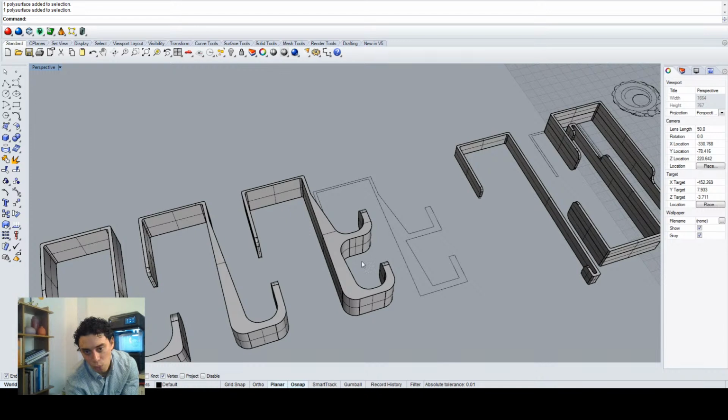I already knew what the thickness right here in the actual hook area was that was going to work for me. What was the simplest way to print it? I already learned about the orientation, the limits even that I had when creating these radiuses. Since I'm going to be printing this part, I wanted to print it without supports, right? So there's a limit to how steep I can make this curve, this radius, before it starts requiring supports.